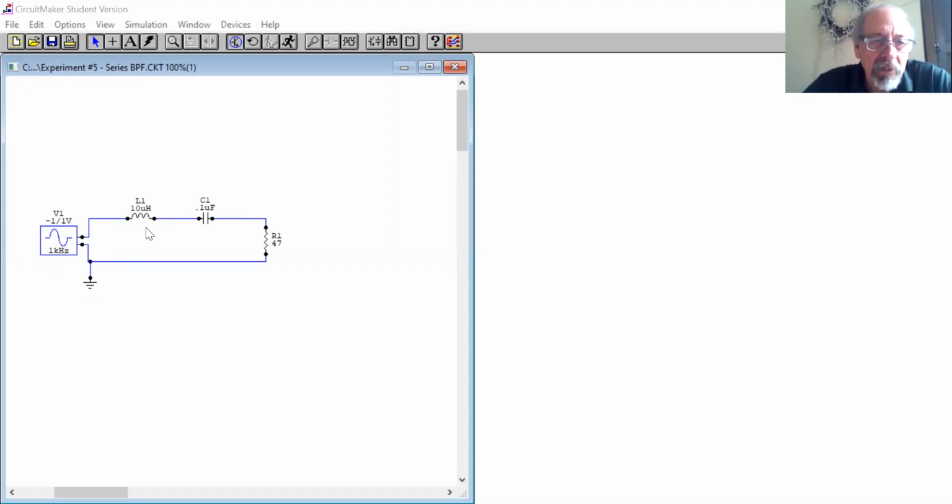Remember, I like to talk about Eli the Iceman. That's ELI, voltage leads the current in an inductor, and the Iceman, ICE, current leads the voltage in a capacitor. So Eli, the voltage can change instantaneously, but the current cannot. The current changes as the magnetic field gets energized. In the capacitor, the current can change instantaneously, but the voltage cannot. The voltage will build up in a charging curve, time constant type fashion.